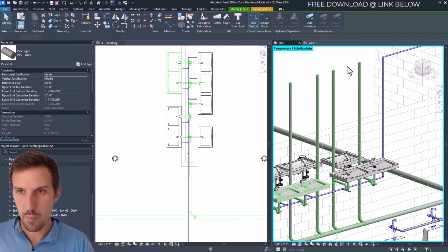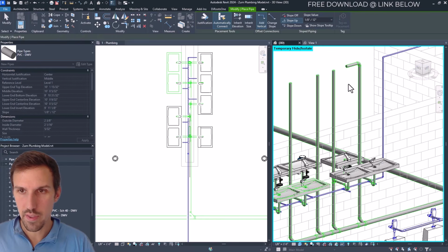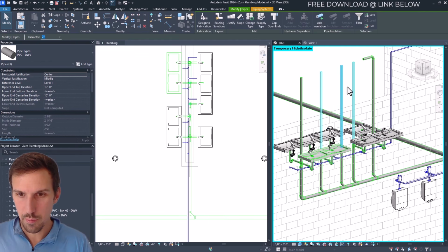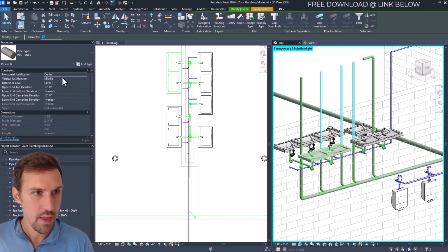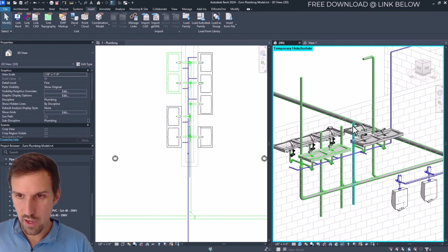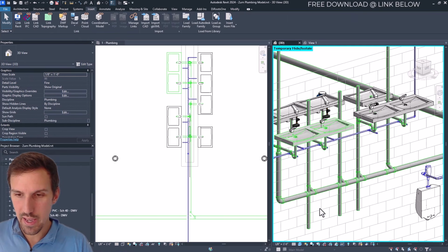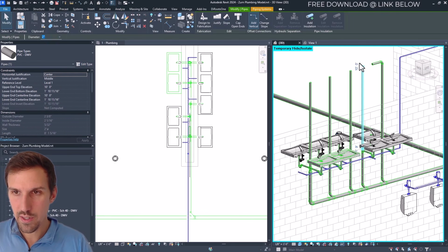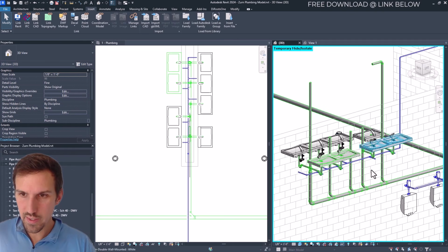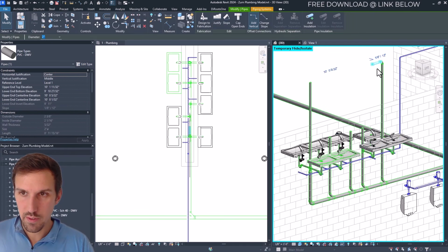So I'm going to right click, draw pipe, and I'm just going to start drawing off in this direction. And then I'm going to change how high all of these are by clicking all of them at once. And then we're going to go to the upper end top elevation. And let's instead make this to, I don't know, 4 feet. And you can see they all drop down. But unfortunately, when I did that, it drops the whole entire pipe. So I don't really want to do it like that. If I just click here and then I click into here you can see that it does make the change. So I have to do these one at a time, just like that.